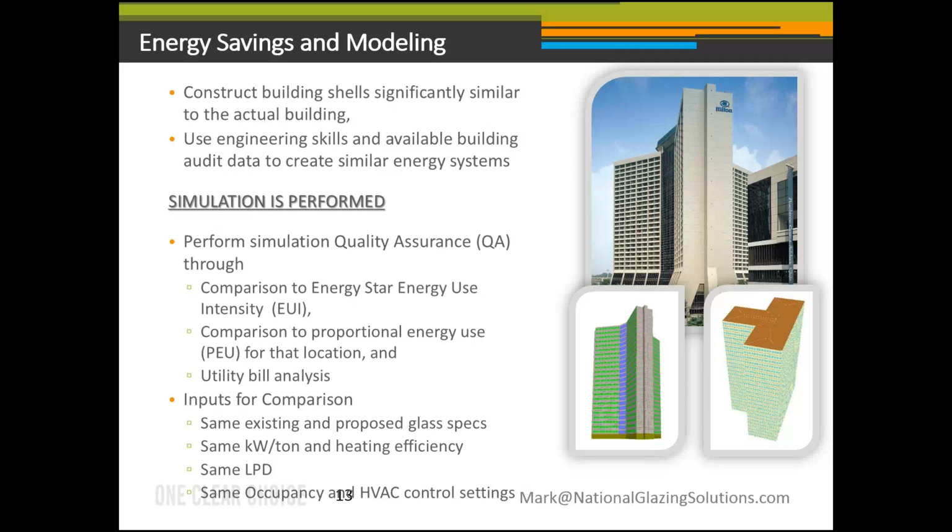It's important to notice in utility bill analysis, we look, of course, month by month at three things: electric consumption, electric demand, and gas consumption. It should go without saying, I've got savings on the brain, that just because the actual annual total at a facility is 1,000,000 kilowatt hours, and the simulated annual total is 1,000,000 kilowatt hours, that is not enough detail, and it doesn't mean anything. So in order to do this work and do this QA, we have our work cut out for us.